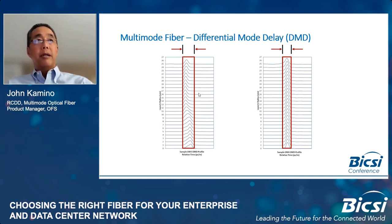That pulse width then is much narrower than the OM3 fiber, and you can space the input pulses much more closely. That means that you have a much higher information carrying capacity in that OM4 fiber, and the bandwidth then is much higher.